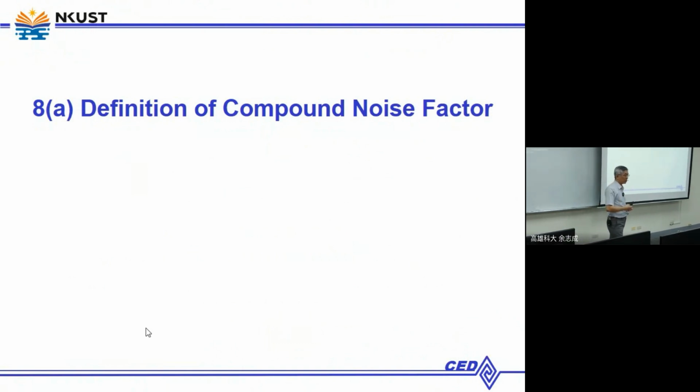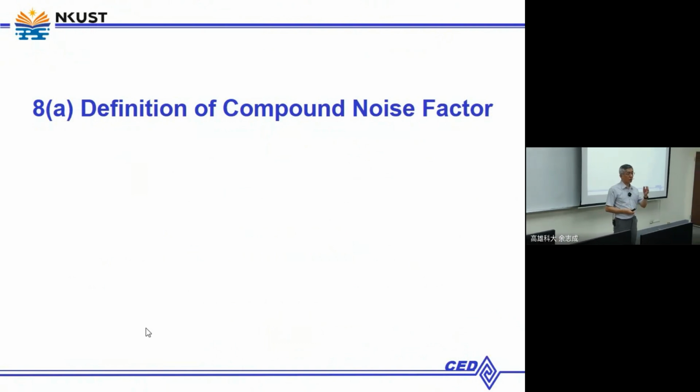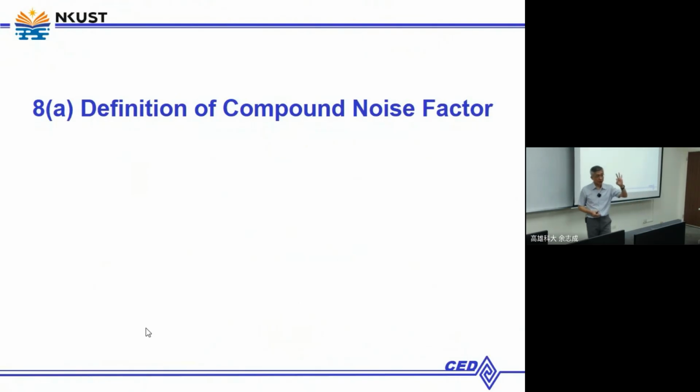In our example, if you are using L4, you can only consider 3 noise factors. If you want to consider more than 3, such as 4 noise factors, you need to use L8. That is in our last homework. We are using L9 as the inner array, L8 as the outer array. So the total samples will be at least L9 multiplied by L8, which will be 72 samples. It is still a lot.